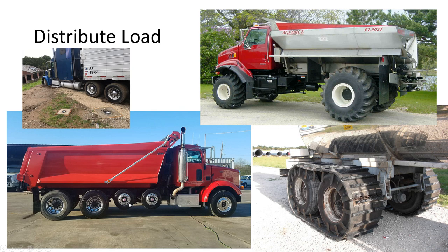They've got these tag axles they can drop down, or lift axles, and there's a switch inside the cab that drops these. So you can go from what your road configuration probably is, which is a front axle and tandems on the back, then you add 2 more axles, and so you can distribute the load even more, right? And so that takes that pressure off of just those, what used to be, I guess, 12 locations where you were in contact with the soil.